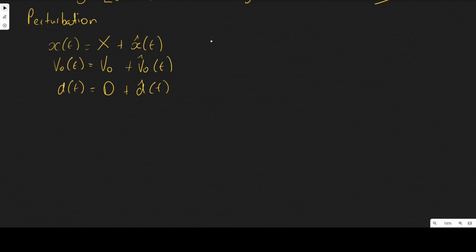As for the input Vs, we will assume that there is no perturbation, so the input will be a clean, for example, 12 volts. There will be no AC components. This will simplify the extraction for the transfer function in the Laplace domain. So we will assume that Vs hat is equal to 0 for this case.